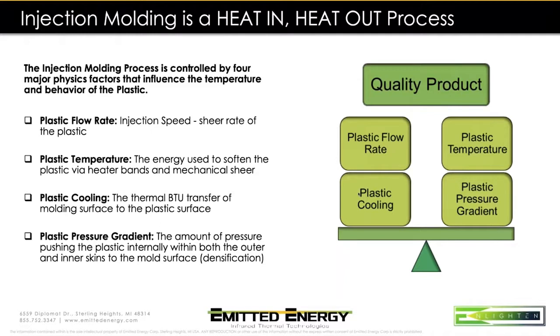Cooling, of course, is key as well, and you're checking that it's working properly in your mold to be able to take that heat out at the proper amount of time. And then the pressure that's involved in that. Your pressure gradient, do you have the proper amount of pack? Do you have the proper amount of fill until you get into secondary pack, that you have the proper densification all around the part? If you don't densify properly, all evenly throughout your part as you put your pressure and packing into it, what you'll do is allow for some slippage in that cooling rate, and you get a chance to get your warpage that comes into play.